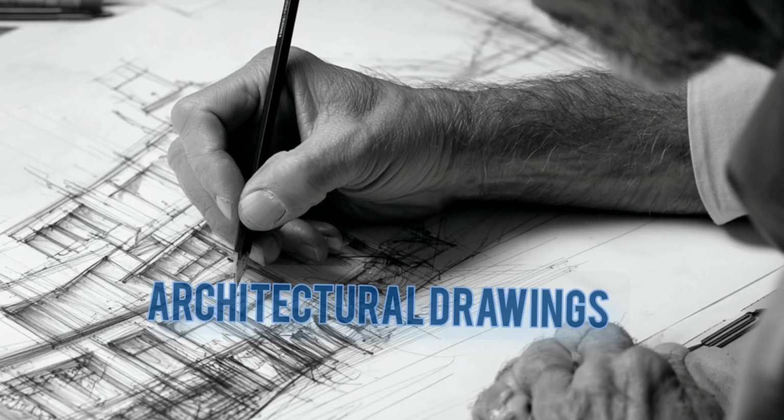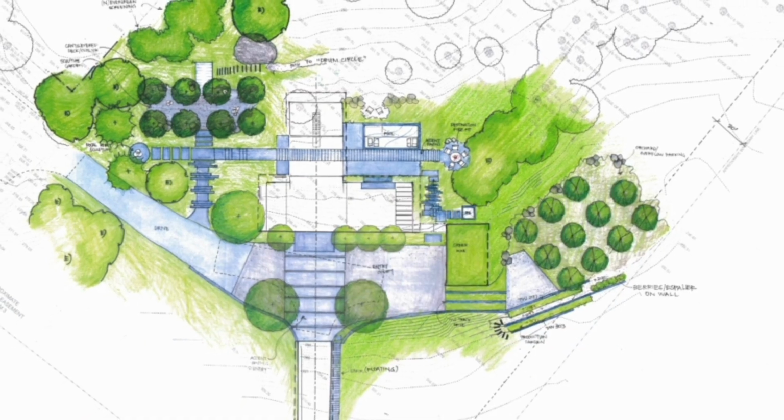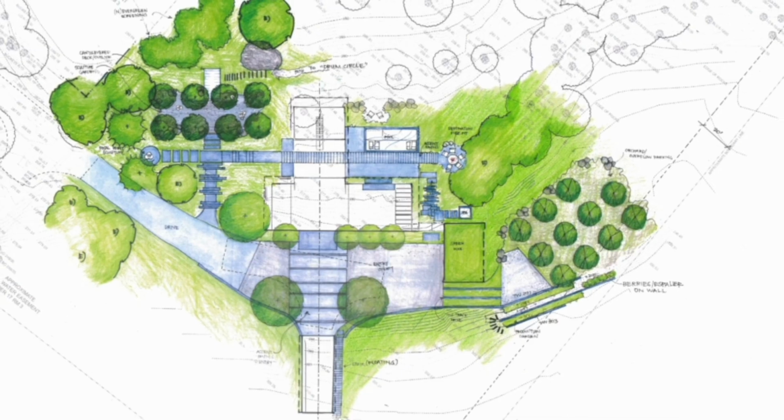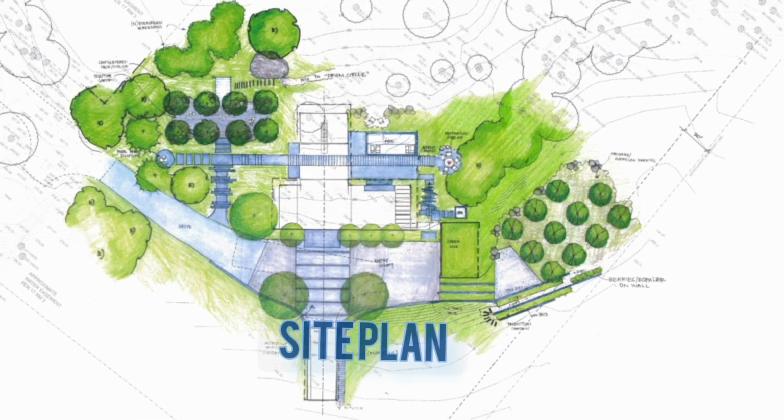Now let's dive into the architectural drawings. As a site engineer, you might think these are just for aesthetics, but that's a dangerous misconception. The architectural drawings establish the spatial and dimensional framework for the entire project. Start with the site plan to understand the building's orientation, setting out points, and finished floor levels relative to the benchmark. Then, move to the floor plans.